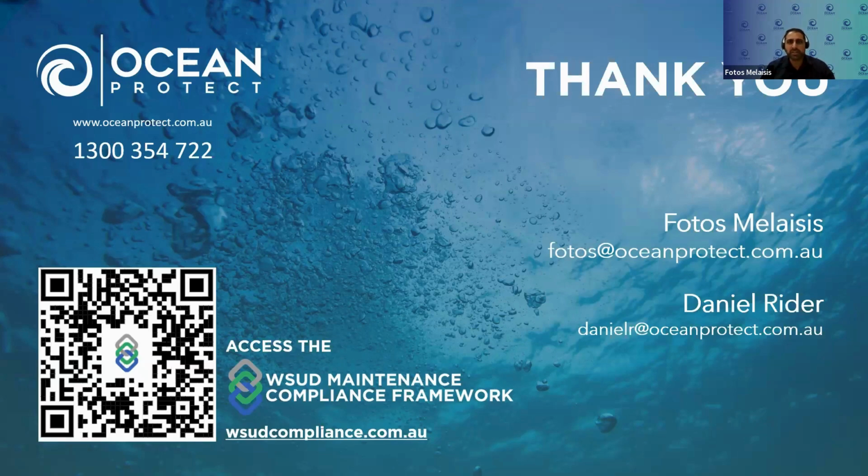So in my experience, it's probably a 4-monthly or 6-monthly cycle where you want to have some sort of visual assessment, and then those first couple of years of establishment is really where you're going to be able to determine whether that annual cleaning cycle is suitable. So in short, no is the answer to that question. It depends. I recall one council, I won't mention their name because I think they're listening in, but it's a GPT that's just undersized. It was one of ours, full disclosure, but a fully undersized GPT, and council need to clean it out after every rainfall event.